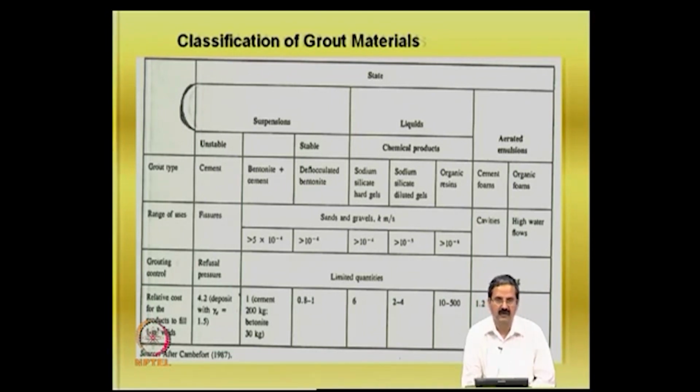One should do a lot of analysis, laboratory testing, and then go for some sort of criteria, otherwise it becomes very difficult. So, one can really do some sort of experiments. Essentially what we are trying to do is that you should take an undisturbed sample from the soil, the material, and then you are essentially looking for strength improvement and permeability reduction. So, you can try different percentages, there are different chemical products here, and depending on whichever gives the best performance according to our criteria, one can choose and then use it in the field with an adequate margin of safety.